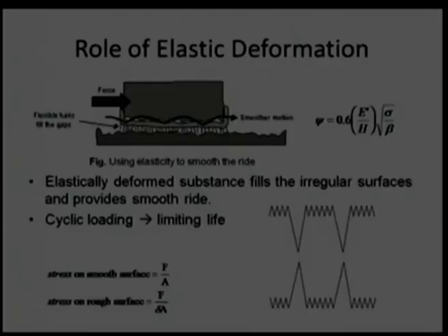However, there is a limitation. We know from the fatigue point of view, if any component is elastically deformed again and again, it will experience cyclic loading and fatigue. If the fatigue has some endurance strength and the stress is more than that, the component will have limited life.